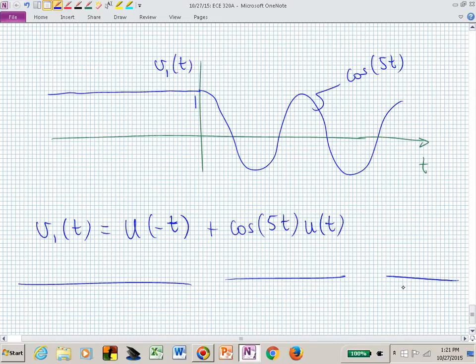If somebody drew that waveform on an interview, you should be able to write that right-hand side down. And if they didn't tell you what that cosine was shaking at, I hope you could measure the period, and how's the period related to the frequency. You could now find the period, let's say from the two maxes, and then divide that into 2 pi, and that would be 5.